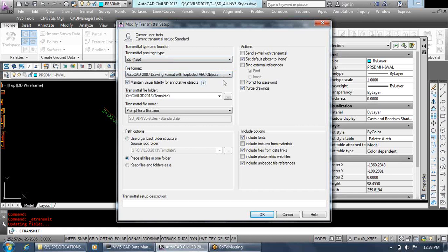I always get it to where it'll crash. I haven't. There's issues with that in terms of there's probably errors in your drawings that are preventing the Etransmit from creating. So it's kind of a bigger issue. You'll probably have to go through and run an audit on your files, and there's an application that Autodesk has published to kind of help with that, and maybe I'll cover that in the next Lunch and Learn.